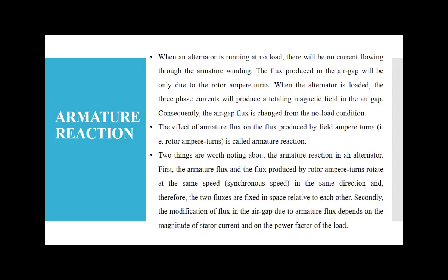Suppose instead of resistive, you are connecting your lights and fans. Fans are inductive loads, as is an induction motor. You have learned about the induction machine, so our induction motor is inductive in nature. So if you are connecting this type of load, then it will be purely inductive, and it will take the lagging power factor. And suppose your load is more capacitive in nature, then your power factor is leading in nature. So here, when we are talking about the armature reaction, we also have to be aware of that.